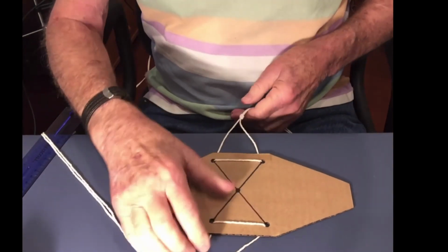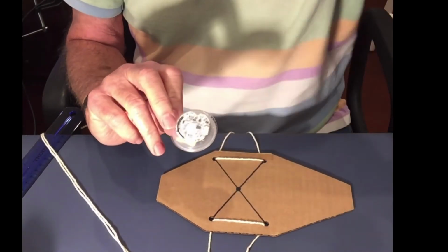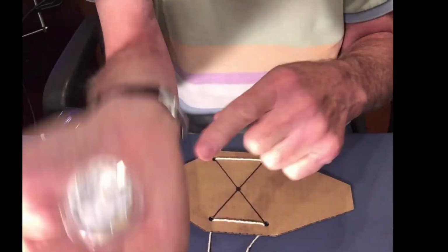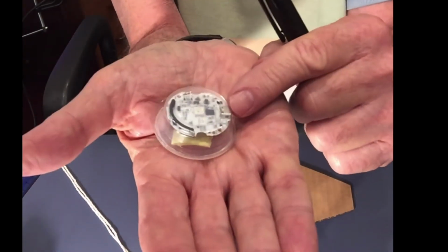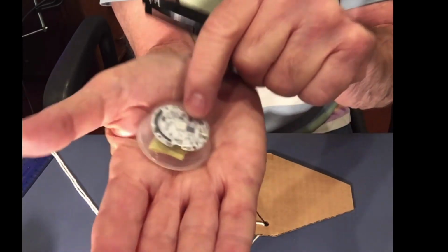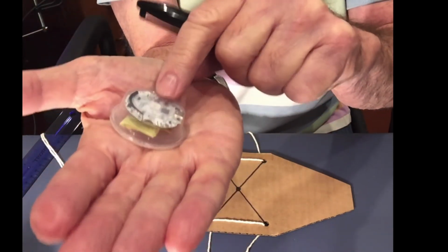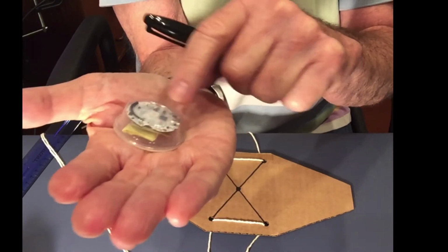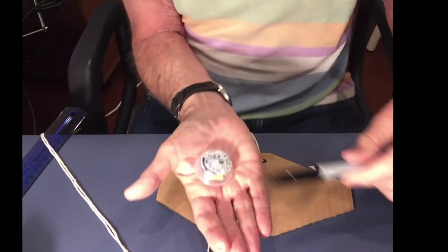So, there's that. We want to mount the accelerometer and the gyroscope. We want to mount the IMU board. To do that, you need to be careful of one thing only. You want to mount it with the big flat side sitting down. Okay, that means you can see the accelerometer and the LED there. You want to pay attention to where the USB port is, because the accelerometer is the tiny little black rectangle sitting right there, just to the right, as I look at it from the LED. On the line between the center of the board and that USB port is where the accelerometer was. And we want that axis to line up with the axis of the board.